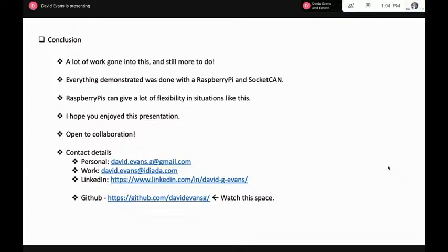But when you press a particular button, it sets a particular flag, or maybe two flags, in that CAN message. I didn't include it in the presentation, but sure, it's just really listening for that CAN message and checking if a particular bit is set, and depending on what bit is set, you call a particular function on the Raspberry Pi. Right. So that module is broadcasting a simple message and just changing a bit if you're pressing the button.